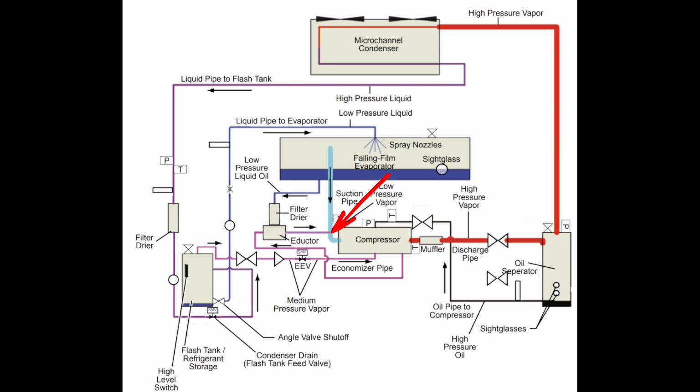This particular machine just returns it to the suction. We've got a screw compressor, so that oil coming back through our suction is expected and is just part of our process. There's nothing wrong with that on this particular compressor. We just don't want the liquid refrigerant to get back to the compressor, but our oil returning isn't going to cause us any issues. Any questions on this particular setup? They're not doing anything here that most other people aren't doing, maybe in just slightly different piping layouts.